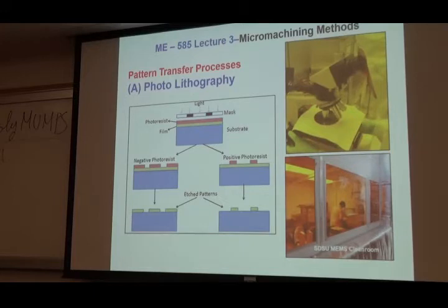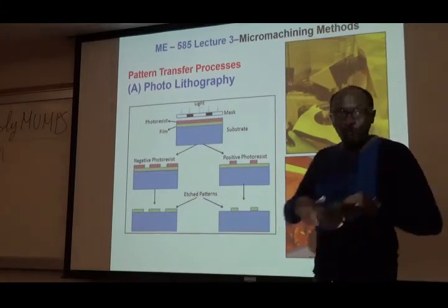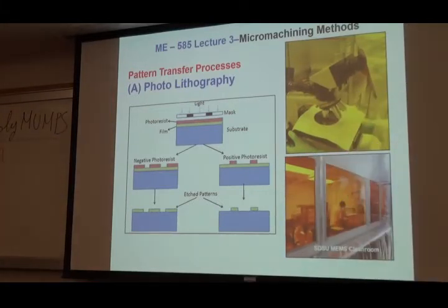So when we do the design project part, I think we're going to have some of you work on some of this aspect. Okay? Yes, Will. When you move on to apply another layer using photolithography, how do you prevent the photoresist from filling in? Well, okay, very good. Remember, in the context I'm describing right now, photoresist's job is being a sacrificial layer, allowing me to do stuff by patterning.